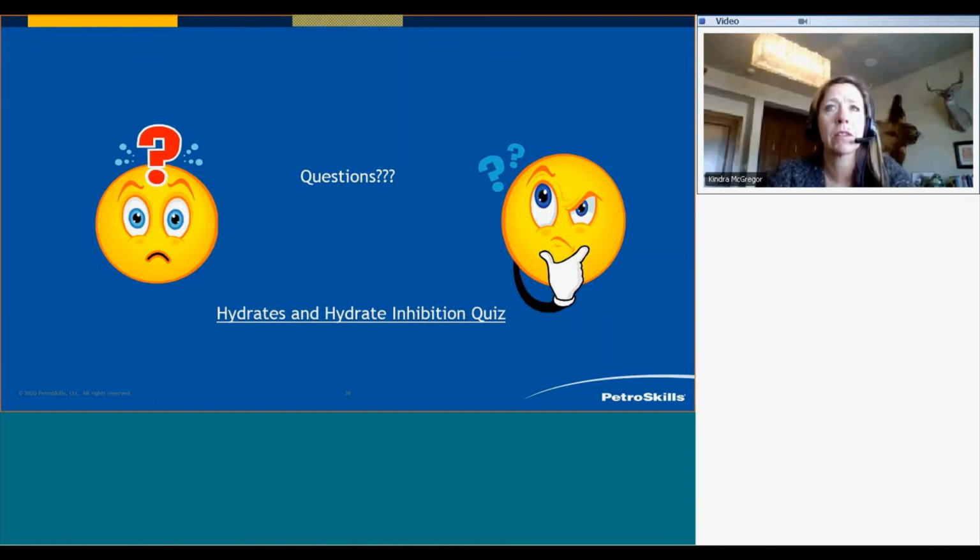So that's a good point to make. Certainly when we're going into very deep depression temperatures, like we would in an NGL extraction plant where we're using mechanical refrigeration, or maybe a JT valve, in those instances we will be over-injecting by at least 3 times to ensure that all of those tubes are fully satisfied in terms of the injection rate.